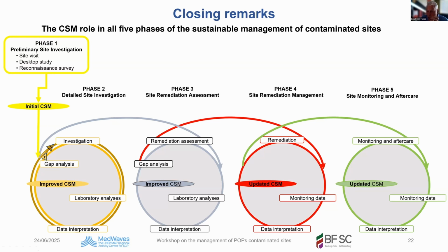You put your question marks. What do I need to know? What do I want to know? And then you have your first detailed site investigation. Investigation, sampling, installing boreholes, installing wells, taking samples of contaminated building material. Then you bring the samples to the lab, data interpretation. Again, gap analysis. Do I know everything? Have I enough information to proceed to the next phase? No, I do not have. So you continue again: gap analysis, laboratory analysis, interpretation, and so on.